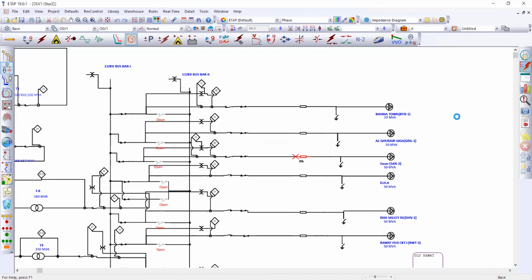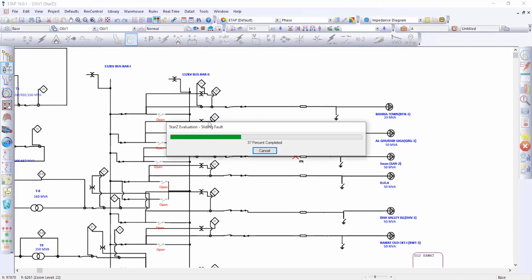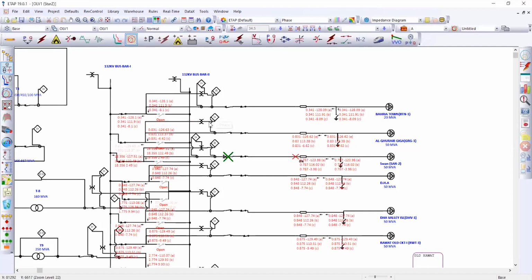As visible here, for the transmission lines whose length is greater than 7.5 km, we have used distance relay backed up by OC relay, and for the transmission lines which have a length of less than 7.5 km, only the directional OC relay is used.